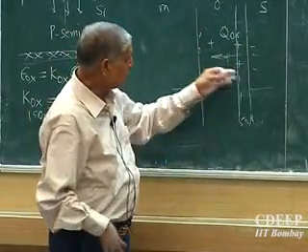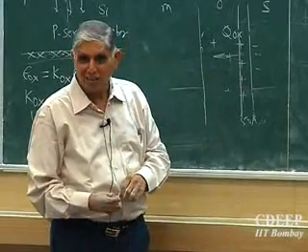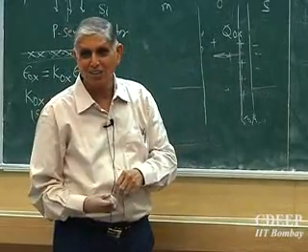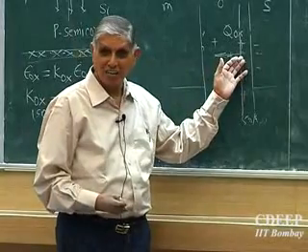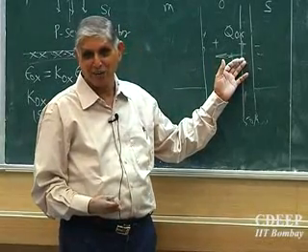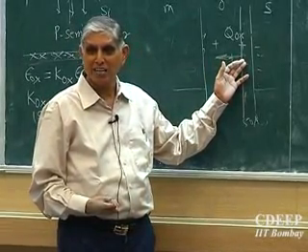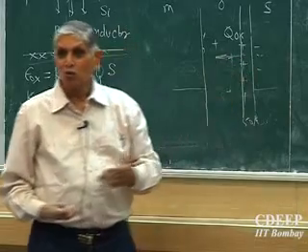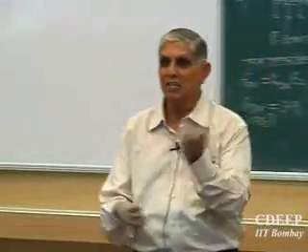So which means charges away from the interface will not influence strongly. Okay. But since mobile charges keep moving, depends on the polarity it sees, so how many will be here additionally, I have no idea at a given time. So what it will vary all the time? Vt. So as the device is being operated, its Vt is varying. Because of the mobile charges are moving, some may come to the interface, some may move from the interface. At that time, the Vt's are not constant.